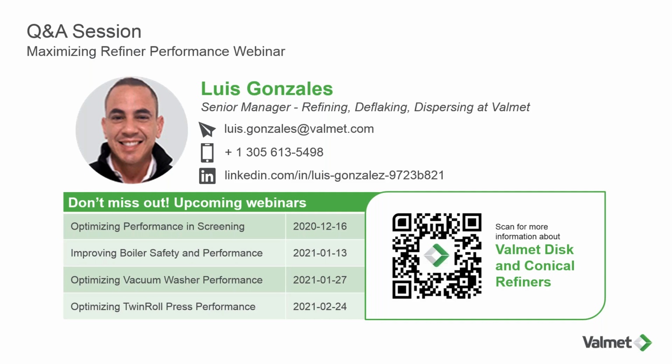The next question is, does Valmet offer refiner audits to identify all of the items that need to be repaired to optimize performance? And how long would an audit take? So yes, the answer is absolutely. We offer both mechanical and process audits. How long would the audit take? On the mechanical side we can inspect 3 refiners per day. So if you have an outage and you have 12 refiners, we're probably going to be able to get all 12 refiners within 4 days.